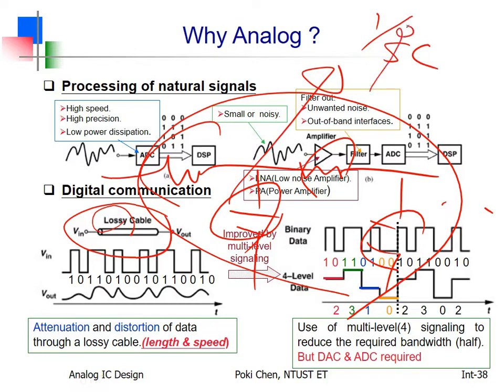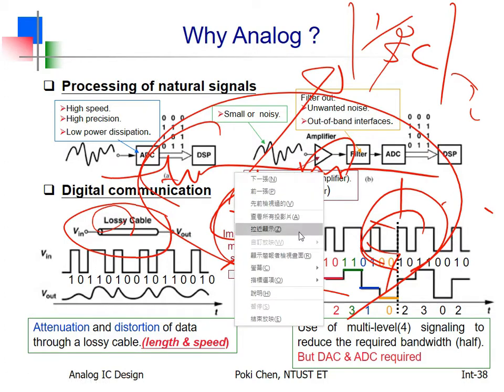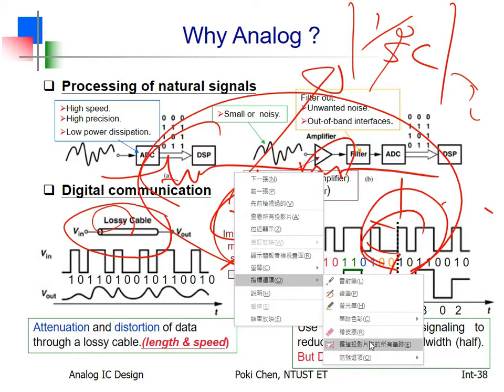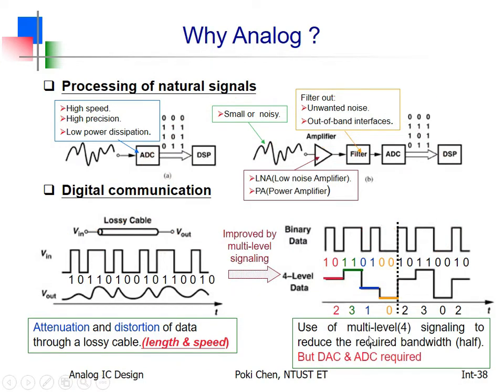The higher the frequency, the larger the s, which means the impedance will approach 0. All the high frequency signal will be shorted by such an RC structure. That is low pass. So it's really harmful for the beloved digital signals.